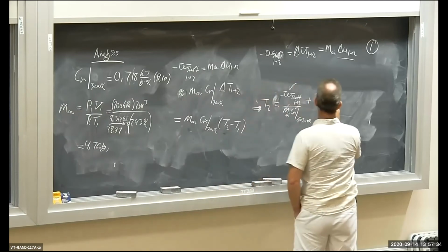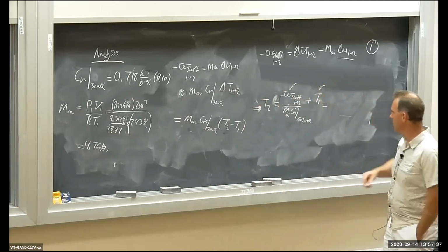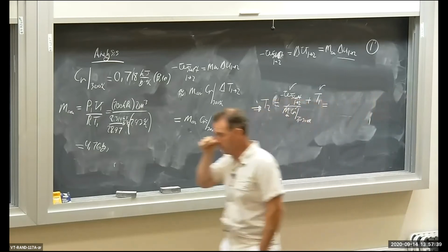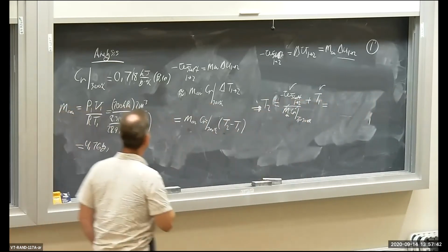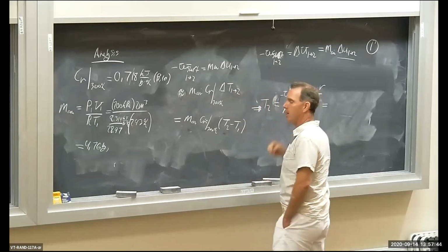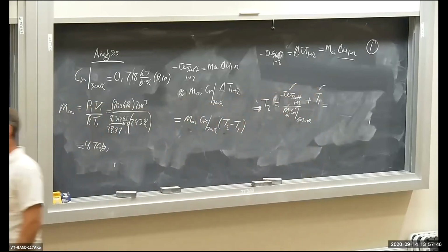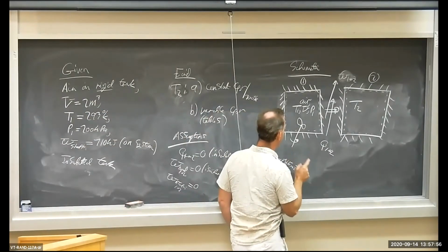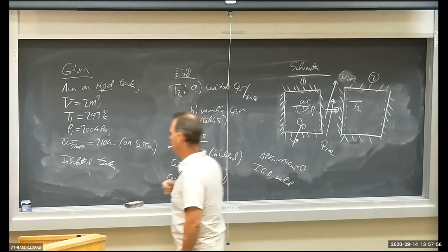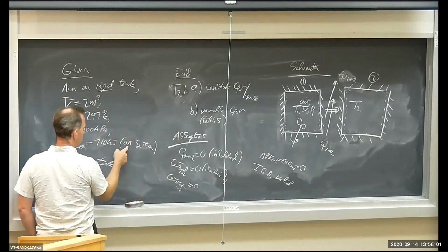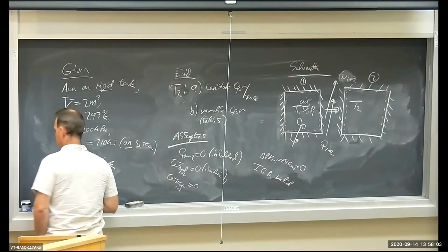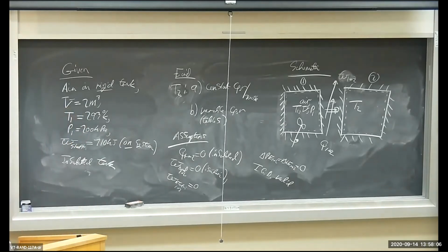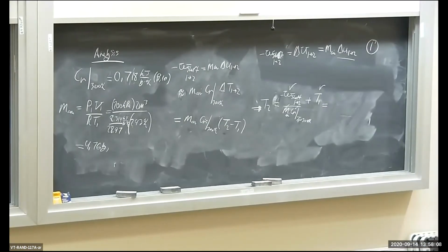Let's see here. Let's plug in. W shaft. Remember the energy balance. In the energy balance, W is by the system. If the system does work, work is positive in the energy balance. We're told that the shaft is doing work on the system, 710 kilojoules on the system. So the numerical value that we're going to plug into the energy balance is going to be negative.